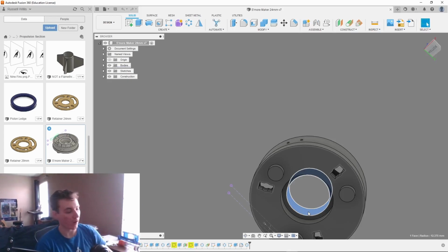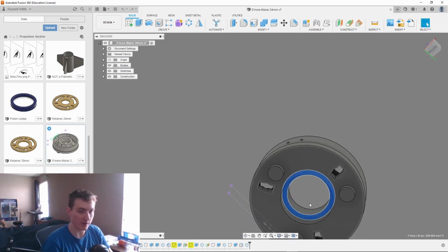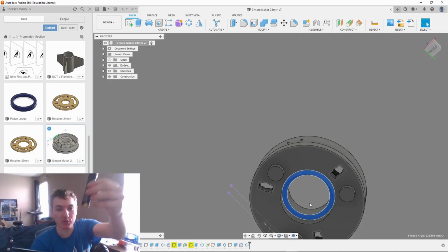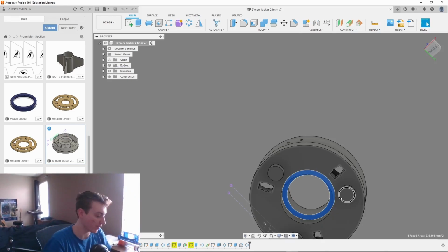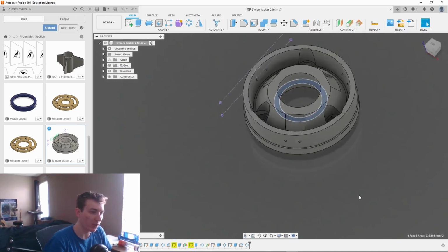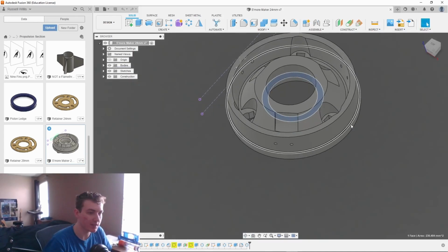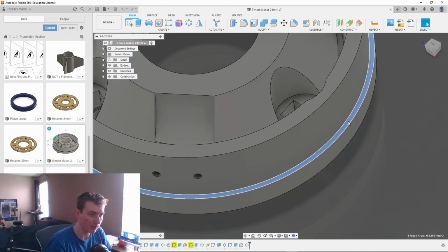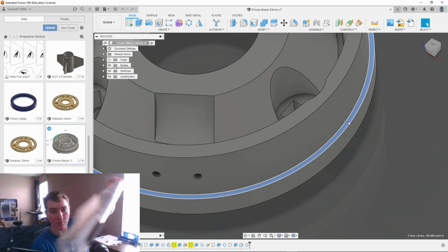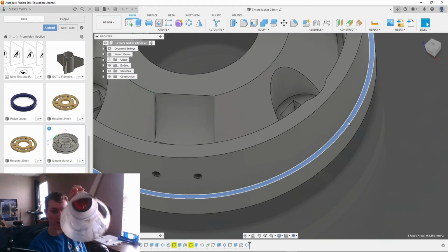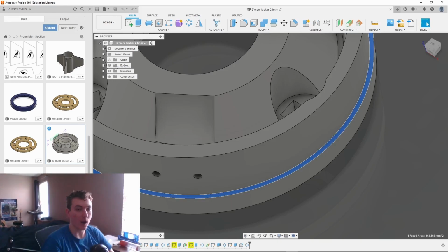Then this surface right here is getting pressed up against this, so that when the motor is under thrust, it's getting slammed into that, which transfers the load to the rest of the rocket. That load gets transferred through the part to this lip right here. That little lip bumps up against that lip right there, causing the rocket to go up.